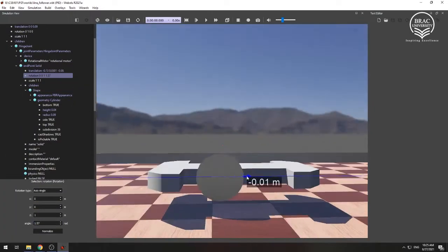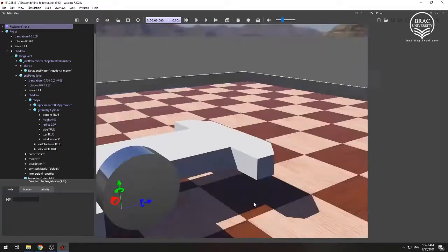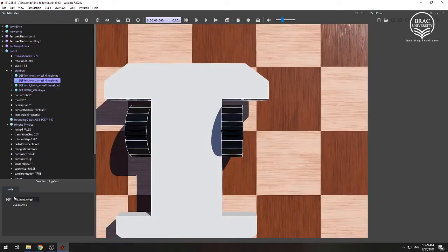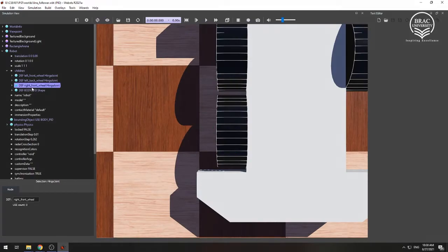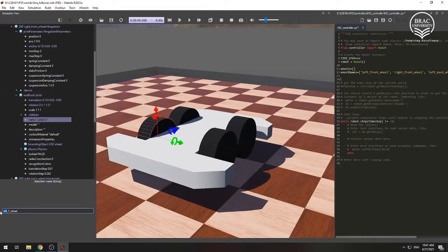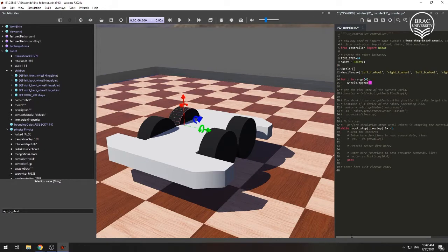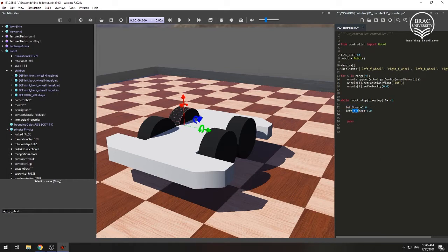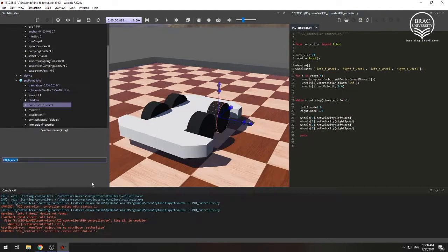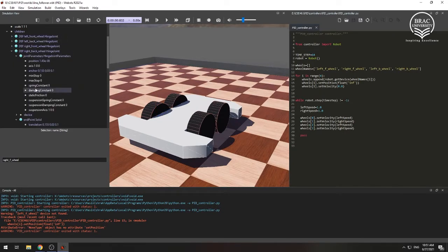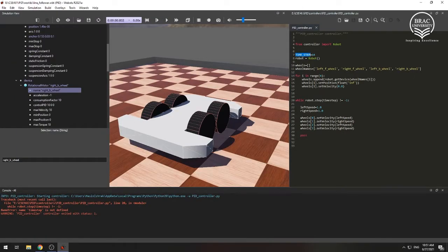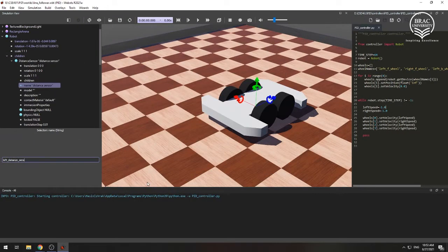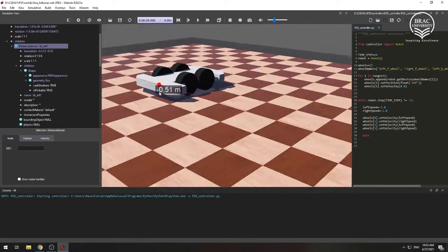I attached 4 hinge joints on the foreside of the robot as the wheels, and they have rotational motor devices at the end, and for the end effectors there are wheel-shaped objects. I also wrote a simple code to test that the wheels were moving in the right direction. Due to the axis in our case, we had to use a negative speed value so that the robot actually moved forward. In other cases it could be some other value. It basically depends on the axis and the robot position in the world, so we had to run a few tests to come to a conclusion.